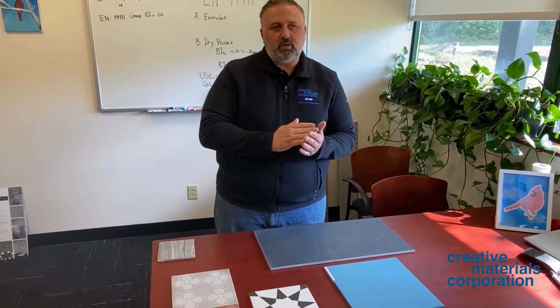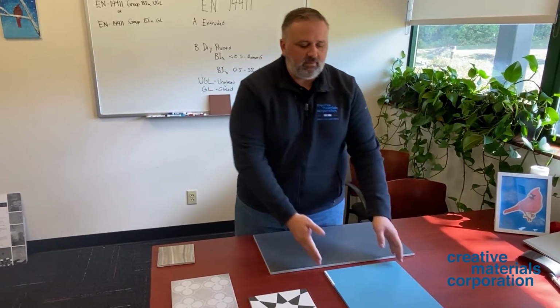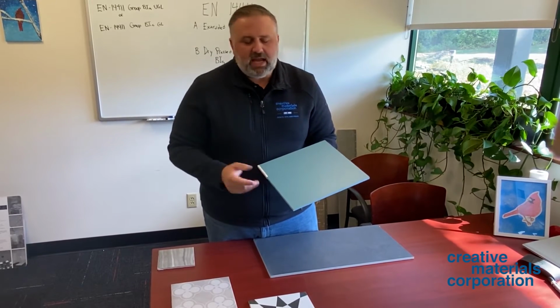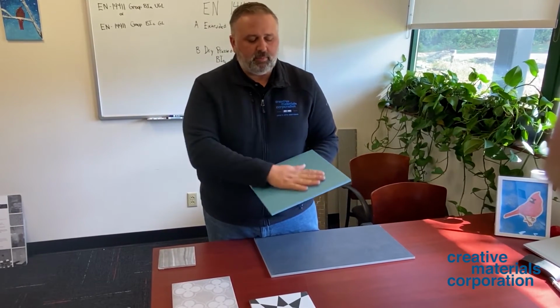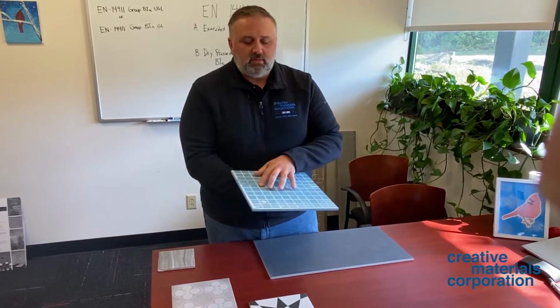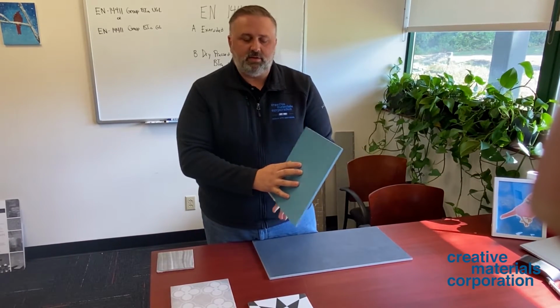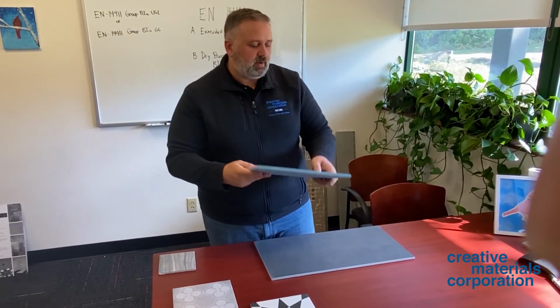When tile first started being produced from a ceramic body to a porcelain body, we started being able to press material with color pigments to have that color go all throughout the body. So this is an original porcelain tile product that we now consider through body, or that's the name we gave it, because if you look at the front and you look at the back, it's the same raw materials all the way throughout. If I were to polish this on the front, it would have a nice shine. It would be this nice turquoise color. If I polished it on the back, it would look exactly the same. There are no glazes on this tile. Technically unglazed, but we refer to it as through body. That's a little misleading now in the newer productions of glazed porcelain tiles, and I'll explain why.